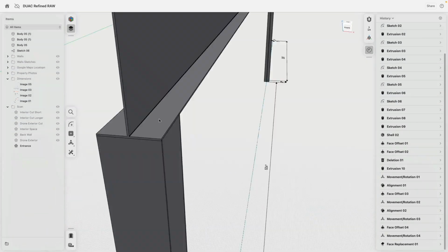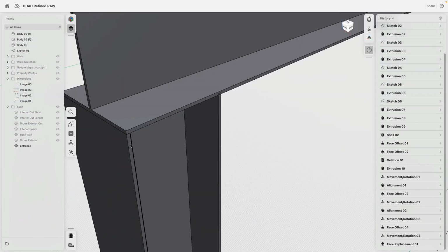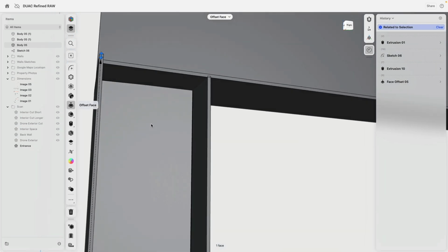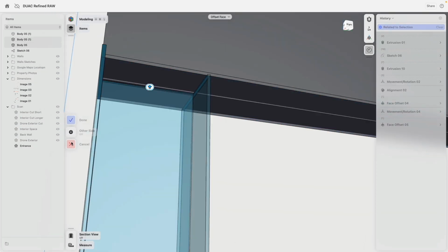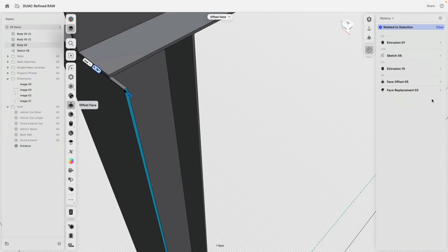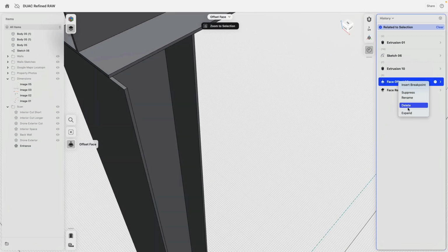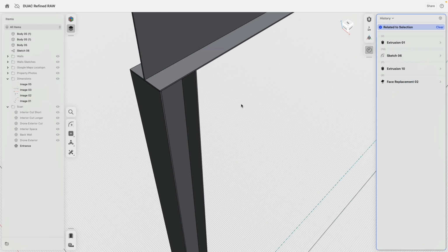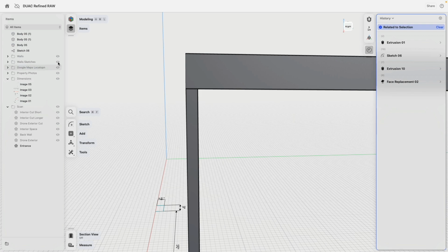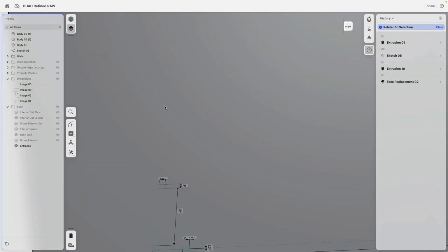And there it's going to be a little bit more tricky. I'm doing a nifty trick. You see how I'm expanding this? So I can select this face, select this, and do that align command. And where's that offset command? There, delete that one. There, perfect, cool.